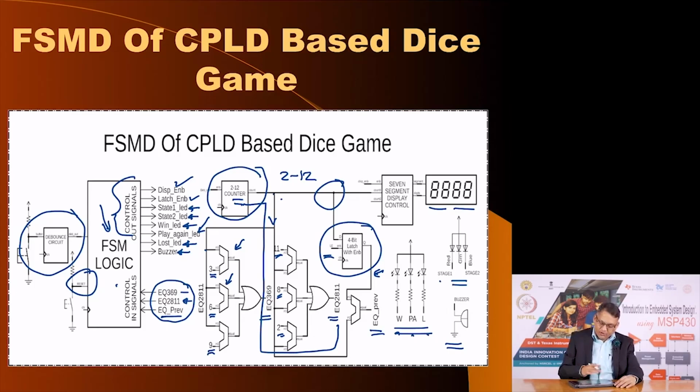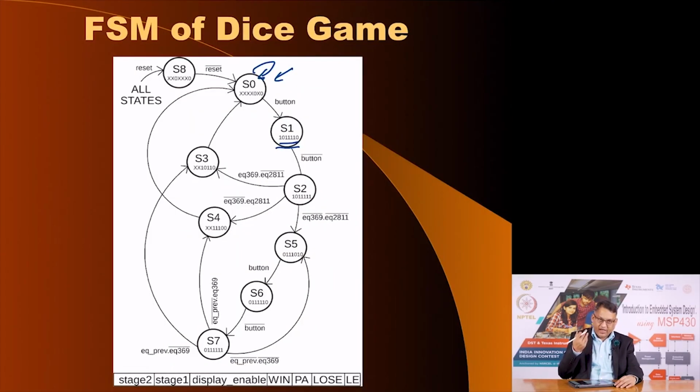So, all these outputs from the state machine are mentioned in each of the states S0 or S1. Now, these outputs are either 0 or 1, but in some cases it is X, which means it does not matter.